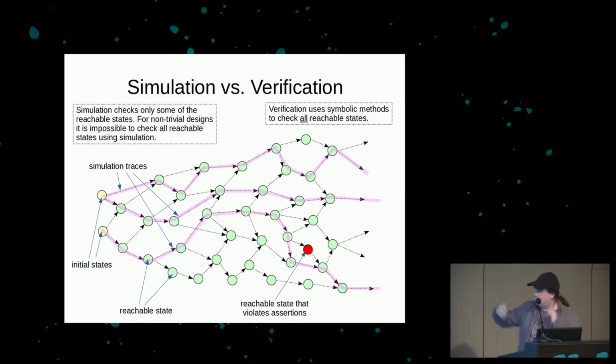One way to improve the coverage here would be just to run more and more random simulations, right? However, if you look at this example really carefully, you will see that there is only one possible path that goes to this one red state. And one of those traces almost got there, but in the last minute it decided to go a different route within the state diagram.